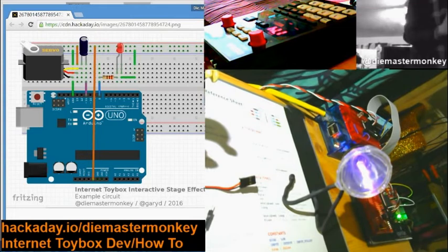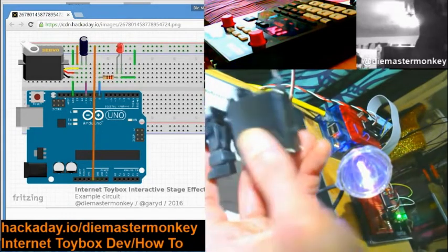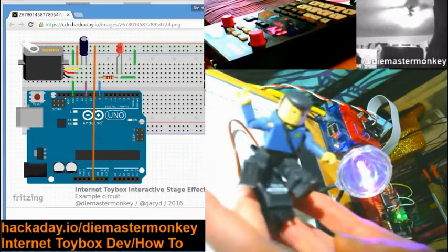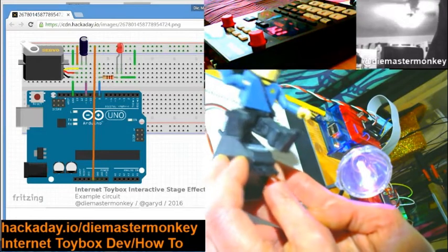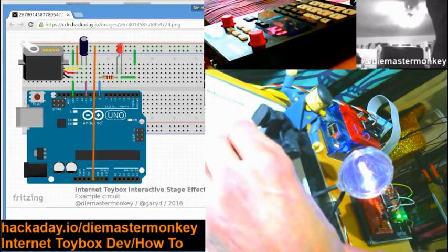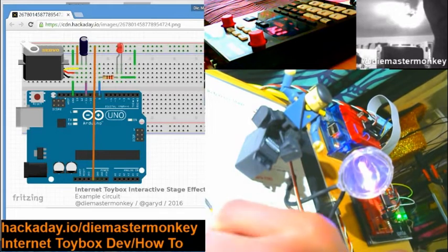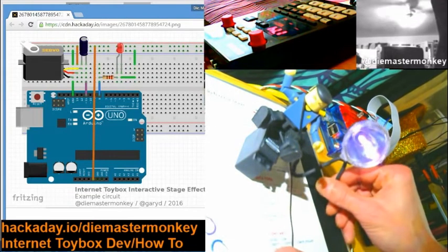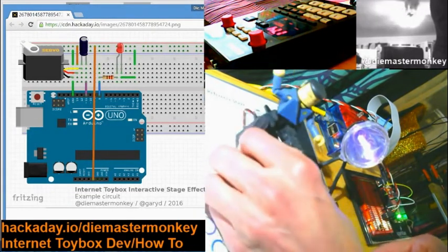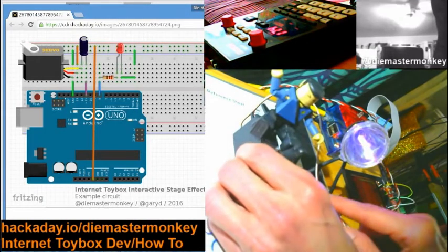Oh, okay, so what we're going to hook up is a servo, and I'm going to recommend that you not exceed the specifications of the Parallax standard servo, at least for this. If you are going to, then you should read spec sheets, because it has to do with the amount of current that is safe to provide directly from the Arduino's power rails. So you're going to want to be careful with that. Now I know this servo is safe. I wouldn't go any higher than this.